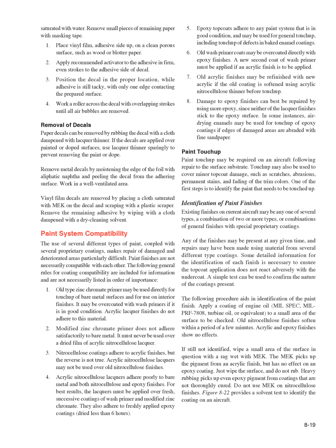interior finishes. It may be overcoated with wash primers if it is in good condition. Acrylic lacquer finishes do not adhere to this material. 2. Modified zinc chromate primer does not adhere satisfactorily to bare metal. It must never be used over a dried film of acrylic nitrocellulose lacquer. 3. Nitrocellulose coatings adhere to acrylic finishes, but the reverse is not true. Acrylic nitrocellulose lacquers may not be used over old nitrocellulose finishes.